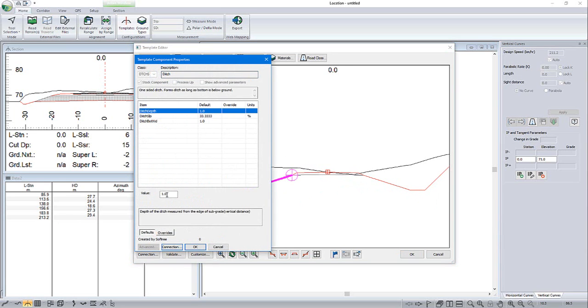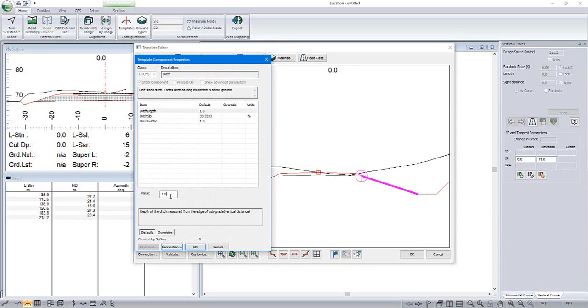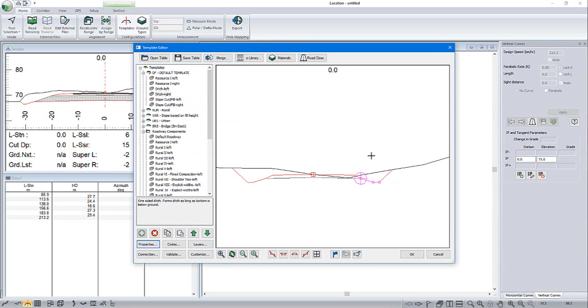again I want to change the depth, for example, to 0.2, and also I'm going to change the width to 0.3. This one was for the left side. Also, let's change these two parameters for the right side. Yeah, this one should be changed to 0.3. And yeah, I think probably this cross section would be similar to the cross section that you want to have in your skid roads.